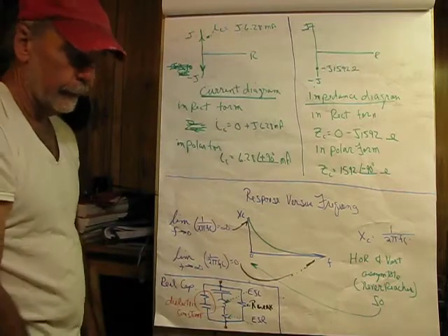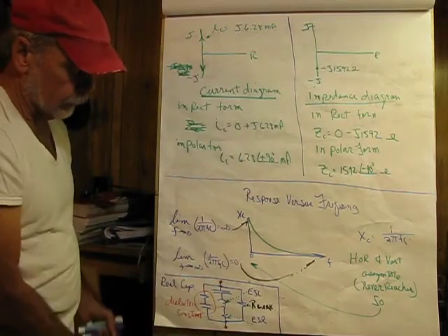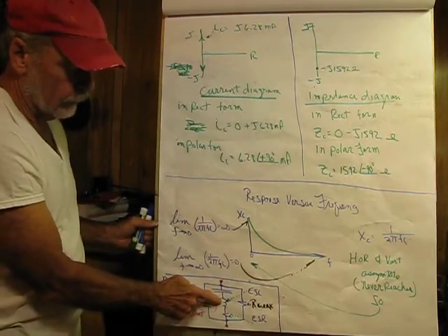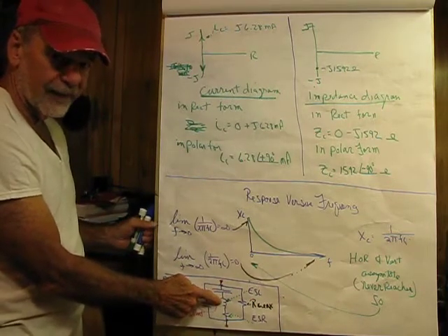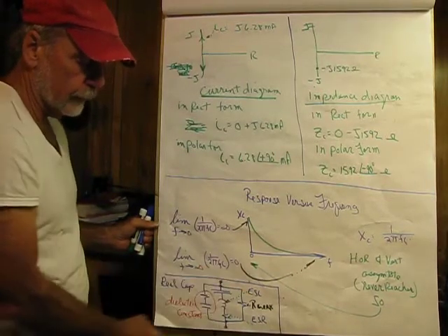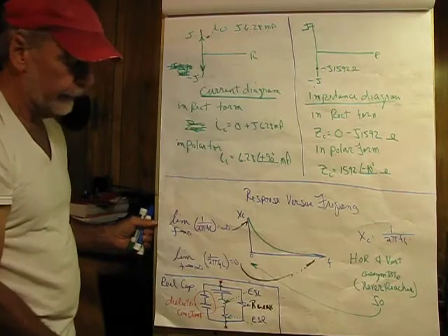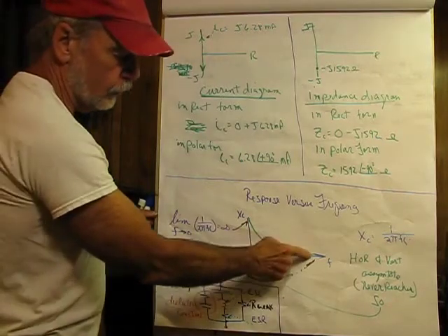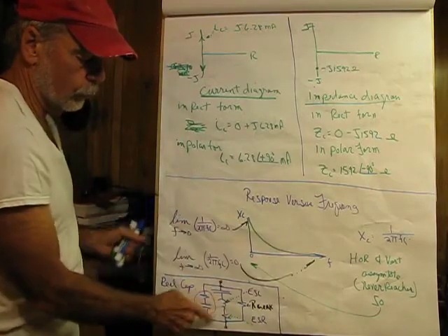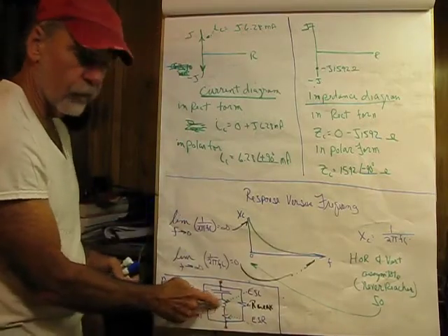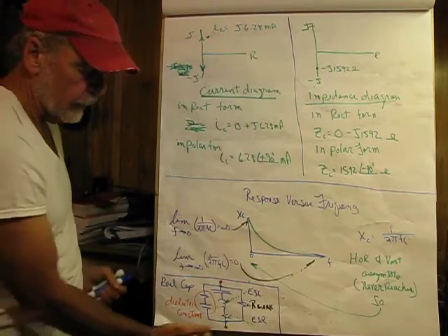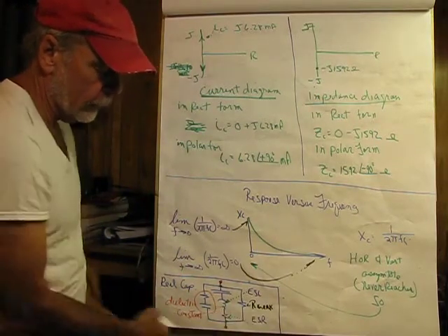Now, what does a real capacitor look like? Not so good. A real capacitor has the capacitor, of course, and in series with it is a small inductance, which is called ESL, effective series inductance. It's there. It causes this, instead of being a pure asymptote, to rise in frequency, because we'll see what the equation for this is, which is proportional to frequency. That's the inductive reactance.